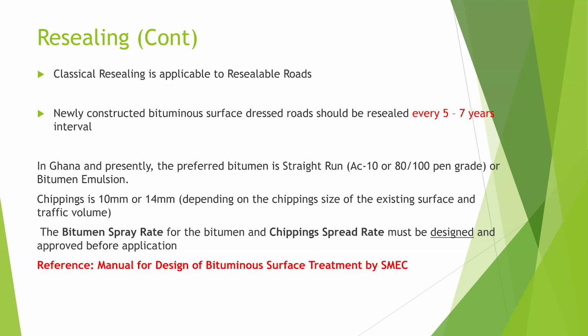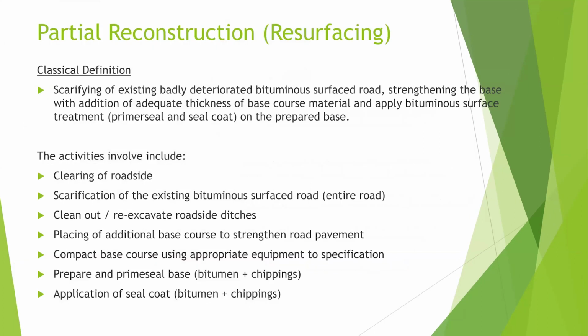The chipping size that is applied is 10 mm or 14 mm, depending on the existing surface condition and the traffic volume. Now, the bitumen spray rate and the chipping spread rate must be designed or approved before application. And the manual that guides is the design of bituminous surface treatment by SMEC. Now, the next activity